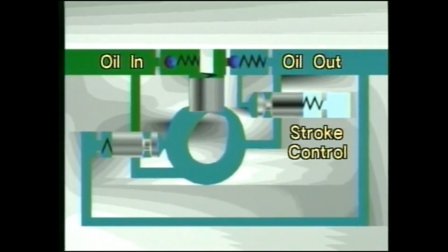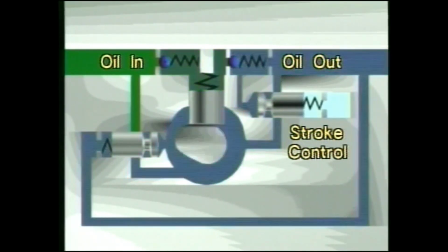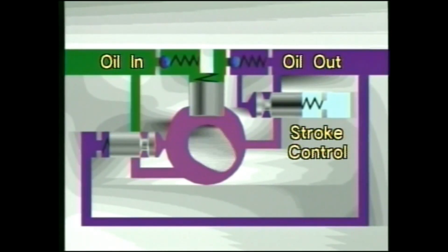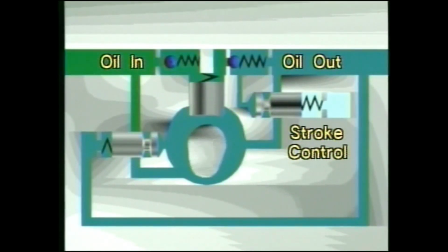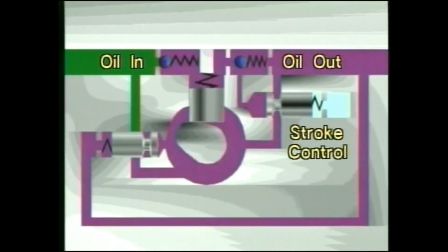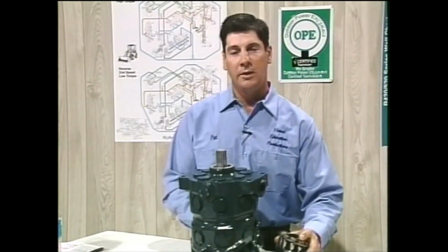Some radial piston pumps vary their pumping volume through a differential pressure mechanism. When there is hydraulic pressure in the piston pump crankcase, the crankcase pressure pushes the pistons up in their cylinders to balance the charge pump priming pressure. Therefore, when crankcase pressure is reduced, the charge pump is able to push the piston downward in proportion to the reduced pressure. The lower the crankcase pressure, the longer the effective piston stroke and the greater the volume pumped.